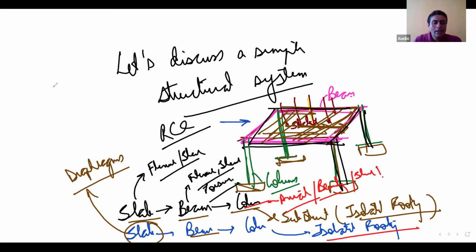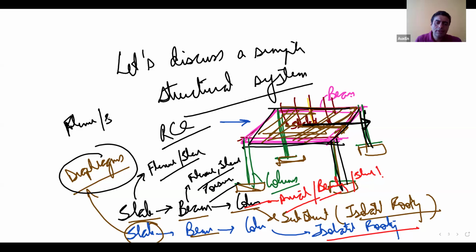Now, if my same slab beam column system had to take lateral loads, which would be the major design action generated in my slab, or now I am calling it the diaphragm, let's say? It will again be moments or flexure and shear, but this time I'll call it the in-plane bending or in-plane flexure.